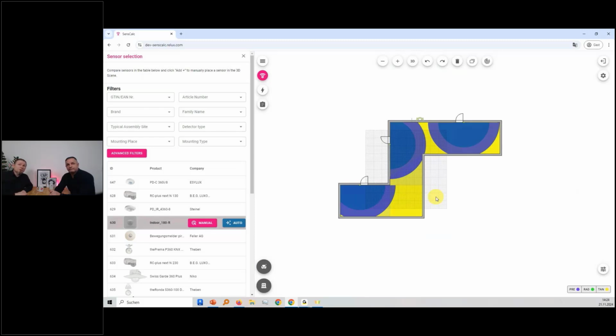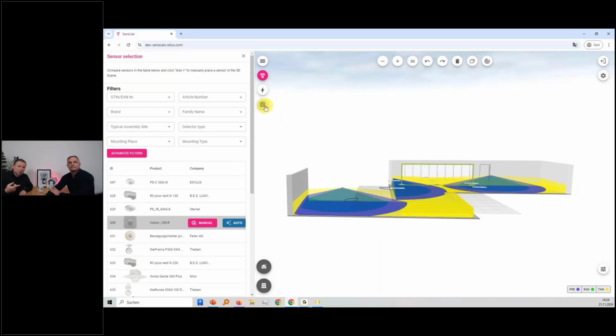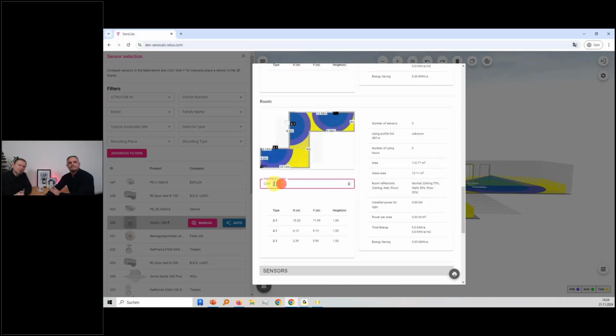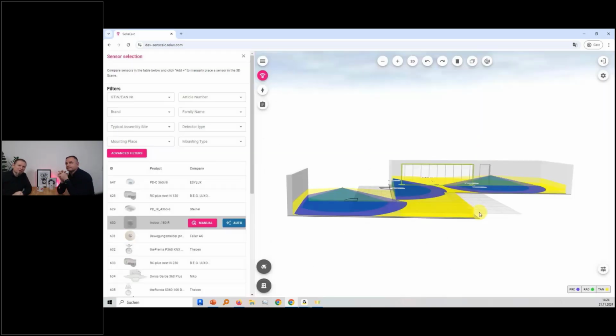Also in Revit, by the way, it's the same. You can use it in Revit with our RELUX CAD for Revit add-on. You can use the same sensor data from GLDF or from the processors from RELUX desktop in sensors. But this nice functionality is automated, the automated placing of sensors according to the doors. By the way, the doors are also recognized when placing a ceiling-based sensor by detecting the room front.